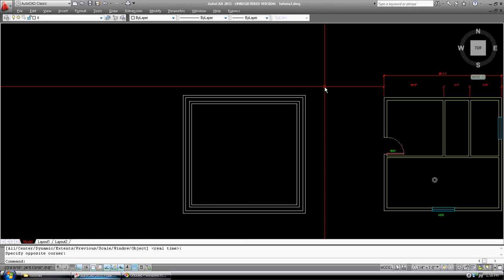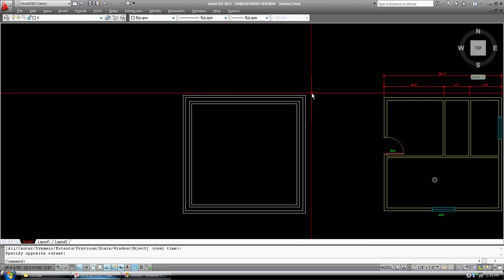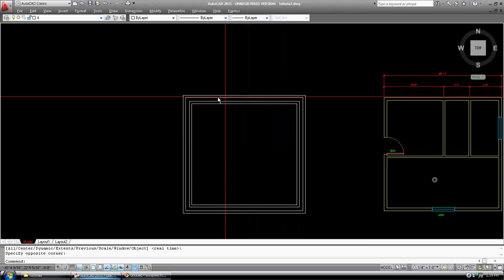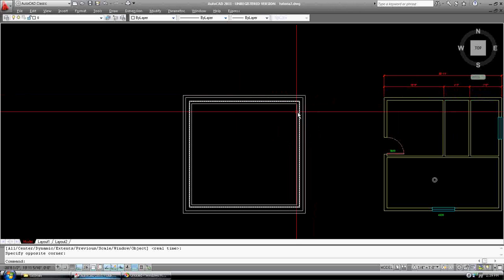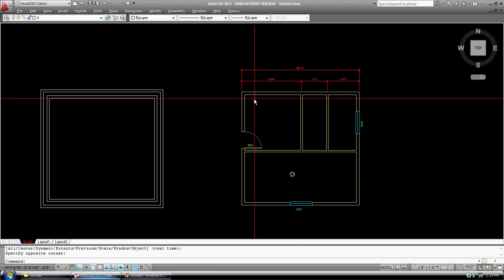As we get into actually drawing a house plan, I'll explain more about footings and foundation walls, and we'll do cross sections and show how all of this works. I would set up a layer called footing and a line type called dashed, and put the footings on that. And I would set up another layer called concrete and put the walls on that.